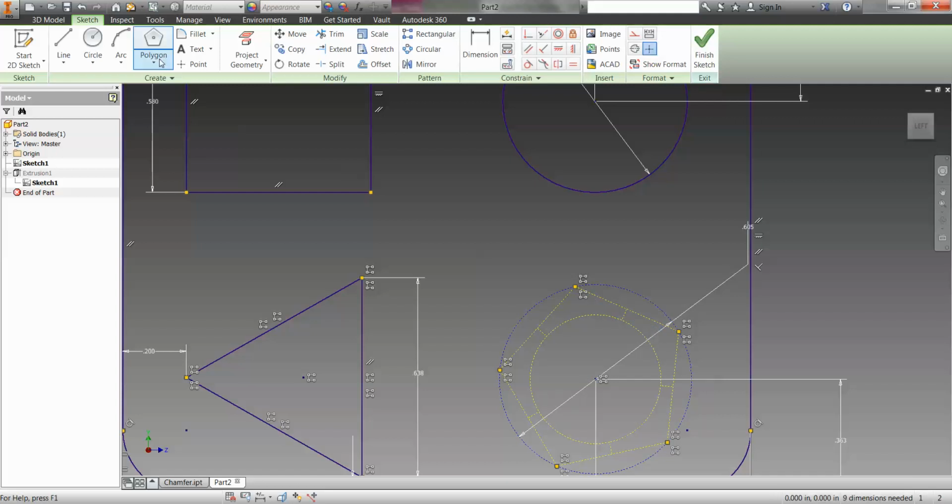Again, if you've already got your star shape made, you can skip ahead in the video. If not, keep working along here. We're just trying to get this all. What probably happened is I don't have a completely closed shape, so I'm looking to make sure that each of these is drawn to the green dot each time so that all of my shape is enclosed. So as I draw this out, it's real important to hit those spots. It's just something that you get practice with over and over and understanding how the program works.